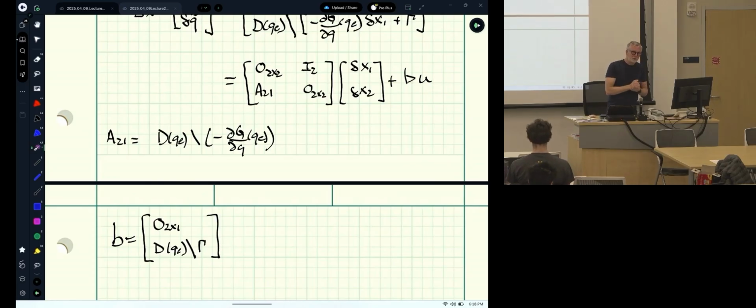Have you balanced your robot yet in Rob 311? I thought you were. Okay, you are. You two are. Have you balanced your robot? It's balanced, but if we add the controller function, it's not balanced. Yeah. So your PD controller is not good because you don't have a precompensator in there, okay? You tuned those gains and it kept getting this wild oscillation. Precompensator, okay? So you guys have seen it on the real robot, I guess.